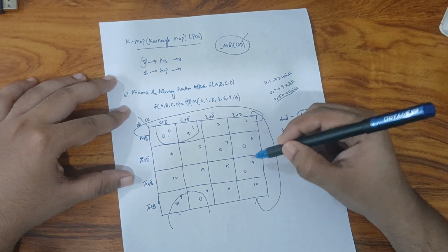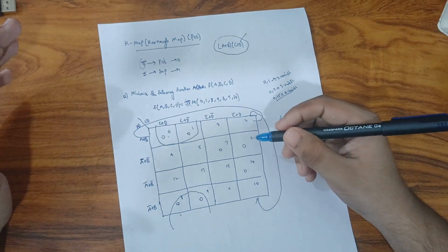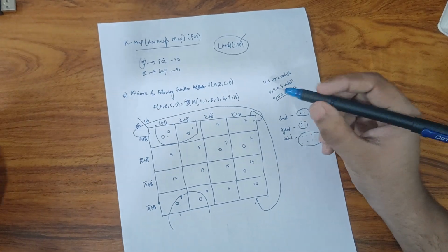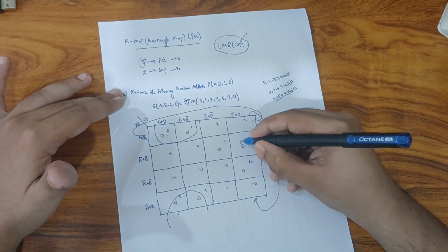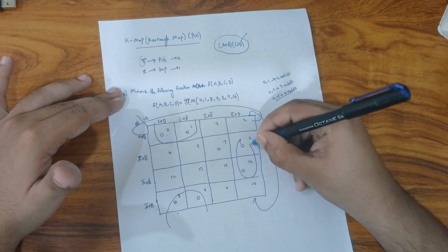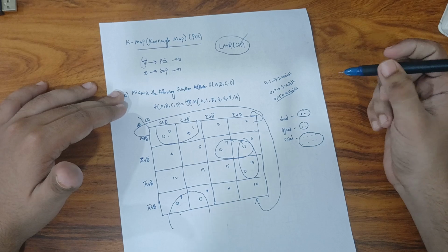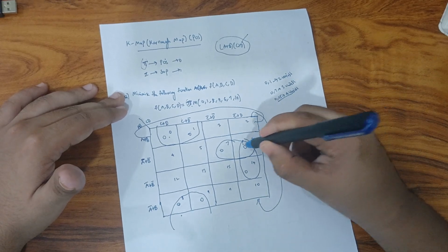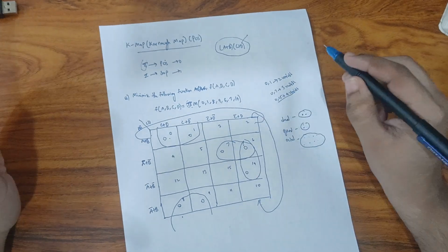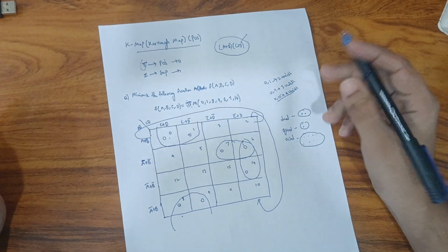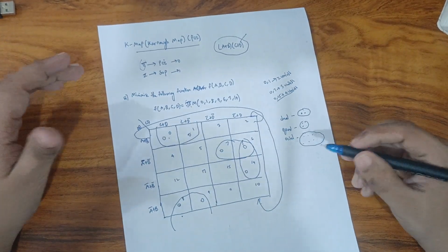So we have three elements. What do we do here? What we could do here is we basically take a common min term for both. So this thing is in the middle, so let us take two duals. Just have a look at it. There we go. That's our group. So we basically took a common min term for both these, and we basically managed to map every min term in the kmap. So let us look into the formation of POS equations.